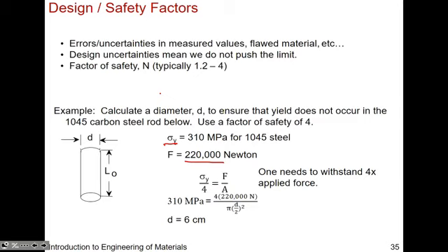So the way you would use or apply a safety factor is, if the safety factor is 4, you can say, okay, well, this material has to withstand 4 times the amount of force, so you just move the 4 over here, and you basically just multiply and scale so that you just over-engineer.